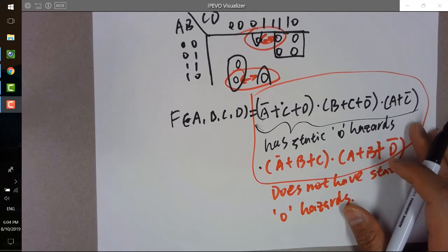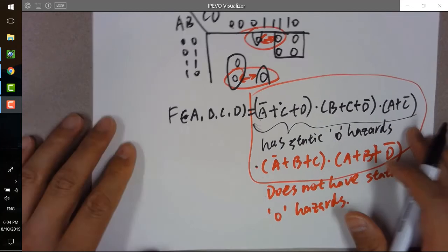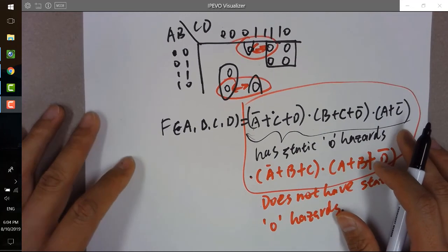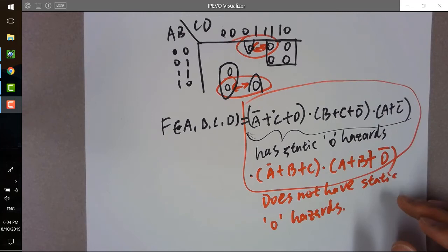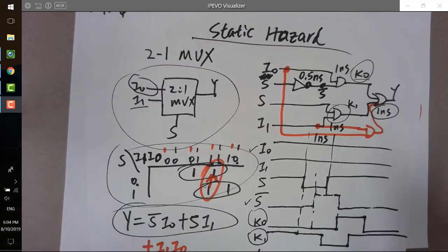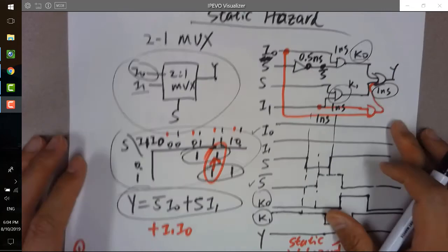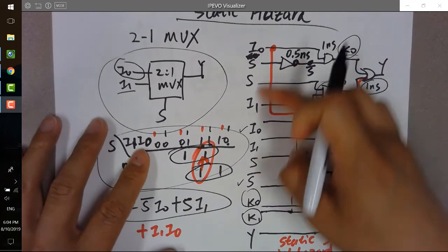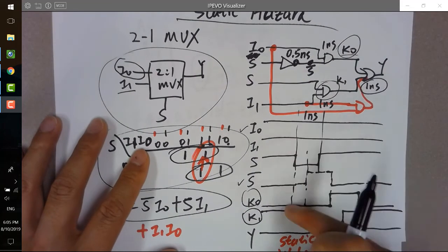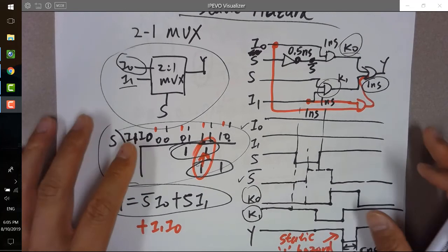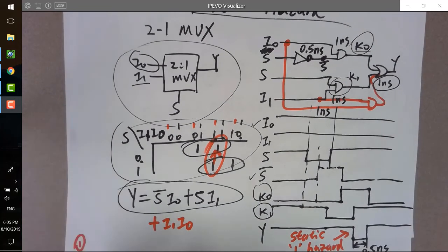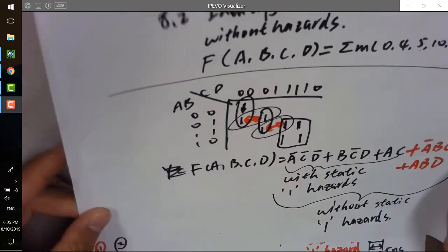All right. I don't think we have time to do the simulation, but if you are running the simulation and want to recover those static hazards, you can refer to the first example on the first page. We have this part, and you have this kind of sequence over here. You should be able to see that little glitch, and you can remove it by adding a term to it, so you won't have that static hazard anymore. Okay, this is how you do it.